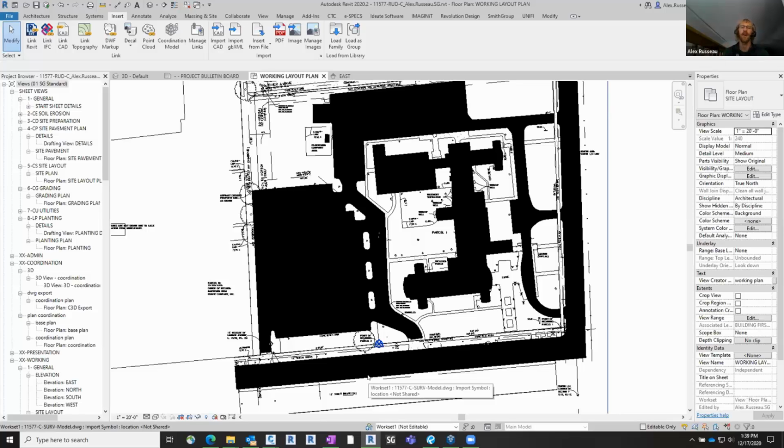Those are pretty much always going to be used on a survey. It's called out somewhere, or control point. Those are two different things that surveyors are always going to be setting up initially in their survey. That way they can be easily replicated by another surveyor when they're going out there to stake things in the field. So those are the two that you want to look for, control points or benchmarks. Each have record data that you can go back to the surveyor to find.